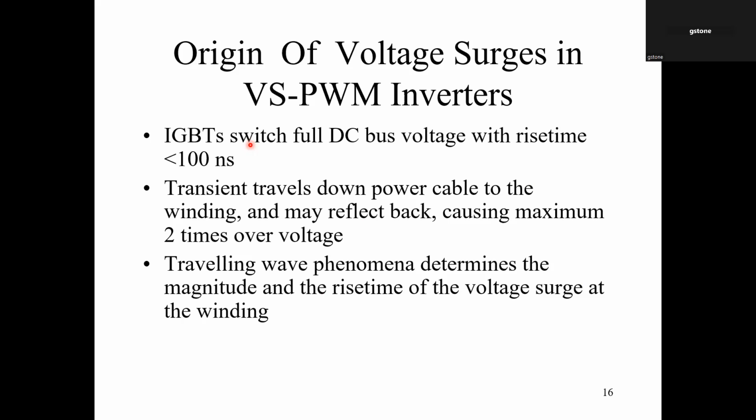And then we can get transmission line effects, because in most industrial applications, you'll have the inverter in a nice, clean, dry, air-conditioned building, and then you'll connect it to the load by a power cable, and that load will be in a messy, wet, humid, hot, noisy environment, usually in a refinery or a pulp and paper mill or a steel mill, and so you don't want the drive, which is full of electronics, near where that motor has to be. So you use cables.